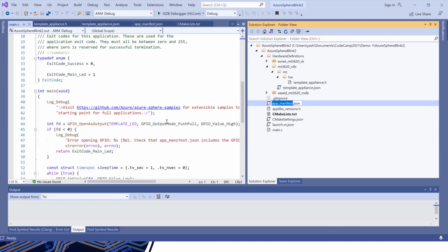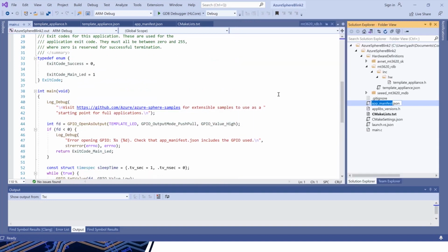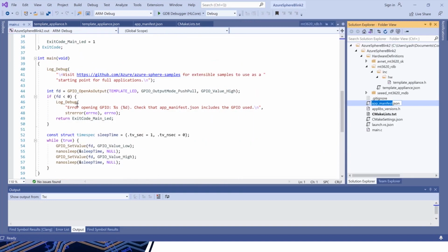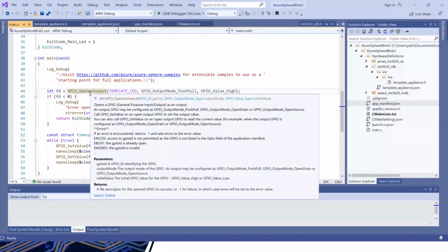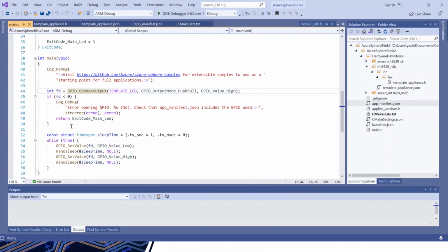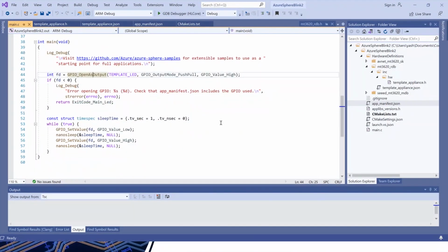Okay, this is a very simple program. By default, it uses the Linux file APIs to write to GPIO, and to toggle the GPIO. So that's what it does, and it uses the POSIX timer. So every 1 second it's going to blink the LEDs. So I'm going to put a breakpoint over here, and my target over here is the high-level debugger core.